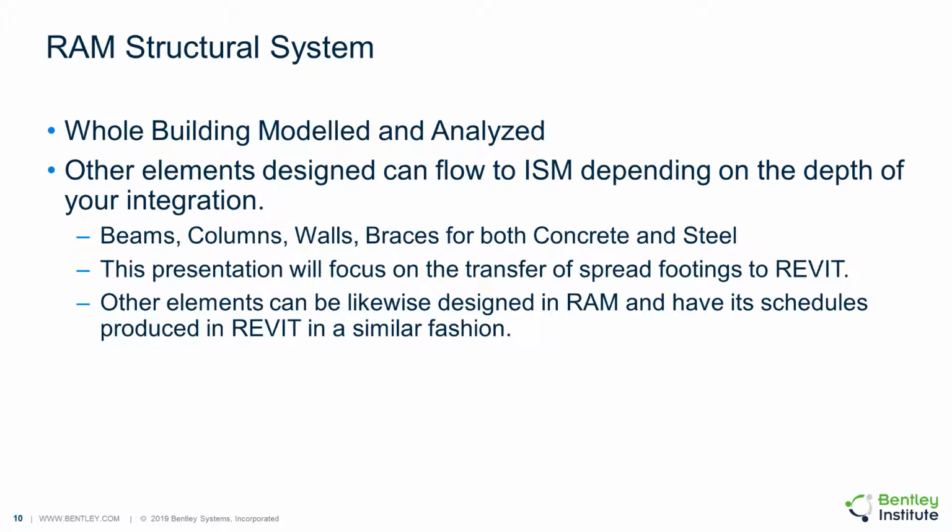Likewise with steel beam columns and braces, we can have that sized and designed for us as well, and have the information transfer out into ISM and to a consuming ISM enabled application such as Revit. But again, for this talk, we will only focus on the foundation design, which are the dimensions of the spread footings, and the reinforcing design as well.